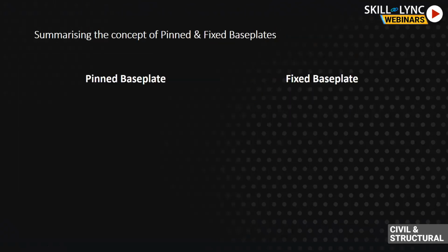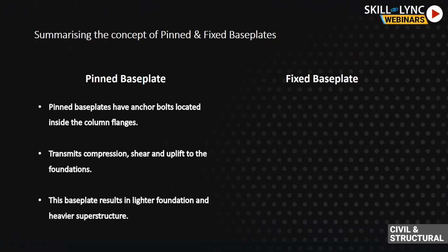the fixed base plates. So the features of the pinned base plate are: it will have anchor bolts located within the column flanges. It will transmit compression, shear, and tension to the foundations. And this base plate will result in always a lighter foundation and a heavier steel superstructure.